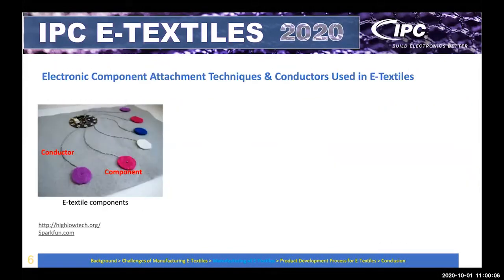Similar to a typical electrical circuit, an e-textile circuit consists of two major segments. There is one rigid area with electrical components and a flexible area with electrical traces where body movement happens. You can think of it like having a central processor in some part of the body, and then distributed sensors and actuators on different parts of the body. These are the rigid components, and then you need some kind of conductors to connect them together so that they can transfer power and communication.